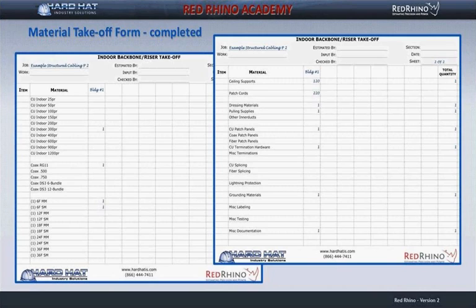At the top of the list is the copper cables 25 pair through 1200 pair. In this example, I included one 300 pair copper cable. The group below that are coax cables. I included one RG11 coax cable. At the bottom of the list are fiber cables, 6-strand through 36-strand, both single mode and multi-mode. In this example, I included one 6-strand single mode and one 6-strand multi-mode cable.